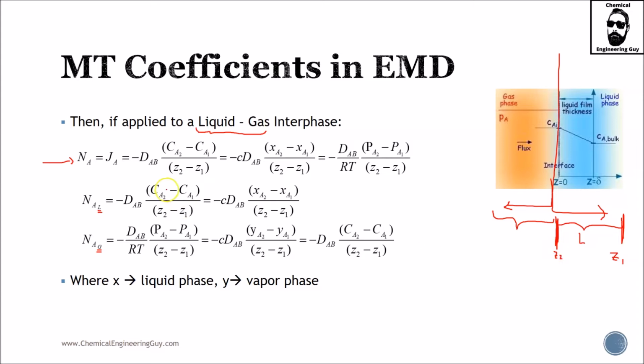What you will see is, of course, we cannot use partial pressures, because we're talking about liquids, so mostly our study remains either in concentrations, difference in concentrations in the path times the coefficient, or molar fractions, which is essentially the same. We just took concentration out of the equation, which is right here. Remember that this concentration can be the total concentration of our species right here. Now we're talking about gas. This is a little bit more interesting because we can now use partial pressures. Now we will be talking about this range right here.